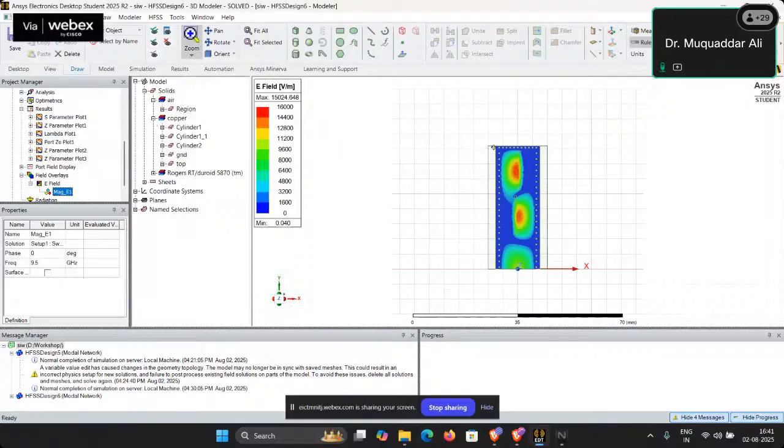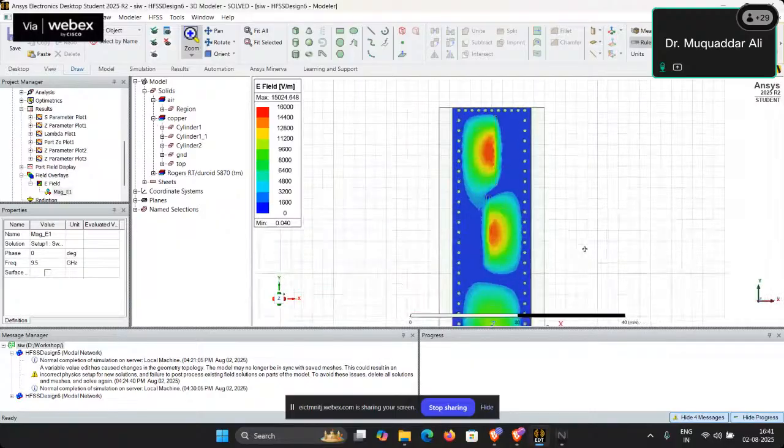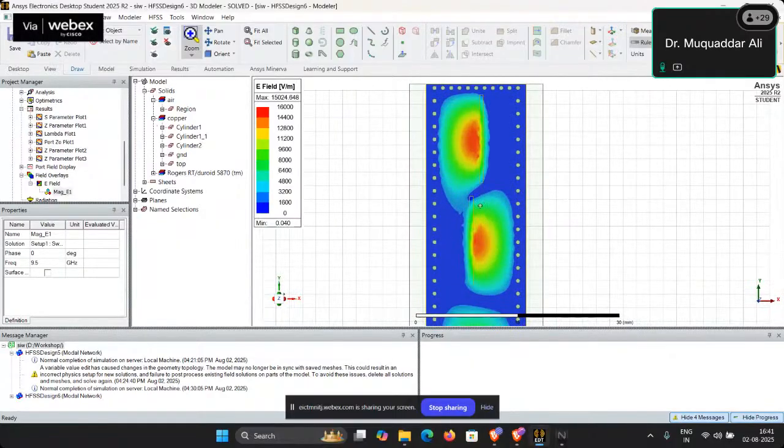another area that we can further explore is this: you see at this slot, the peak electric field is about the center of the slot, whereas here we can see that this slot can be moved to the lower side, and that will increase this field, and that will also help you increase your gain and matching.